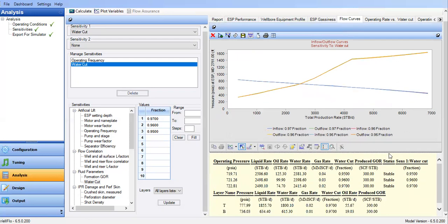In this case, you just input directly. There is no option to assign this water cut to the B reservoir, the new reservoir. In this case, I cannot, unfortunately. So I just put a number and assume that it's the mixture water cut. Let's just input 0.98. Let's say by opening the new layer, I can achieve 98% water cut. What is the flow rate that I get?